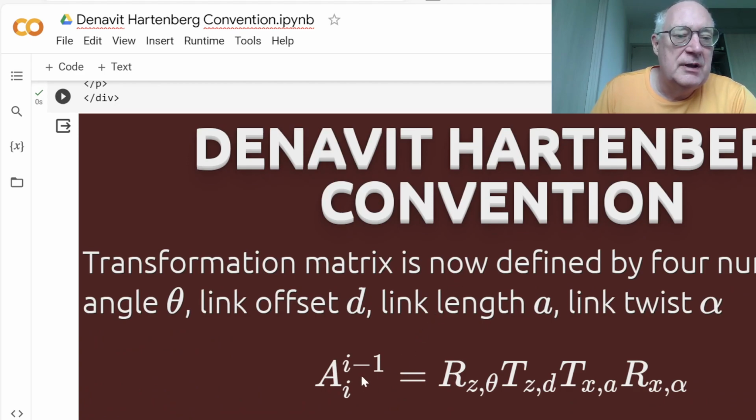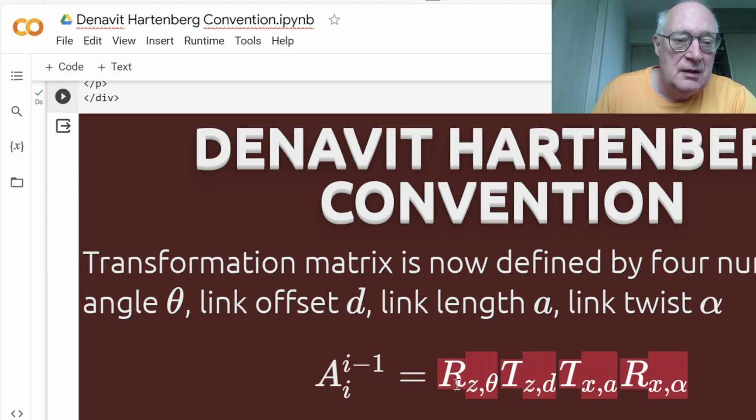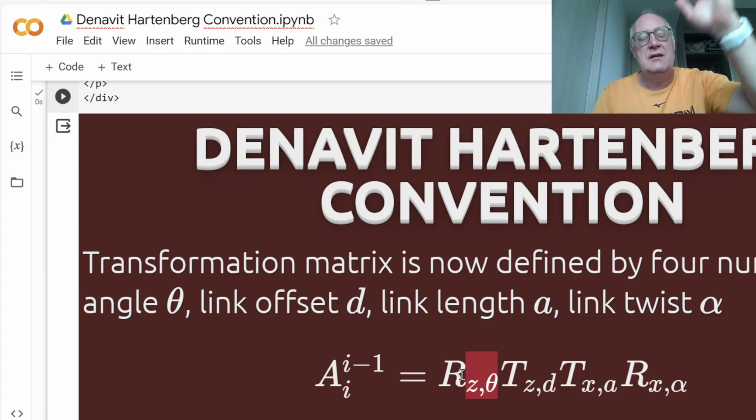So our transformation matrix from i-1 to i is now defined completely by these four numbers, which we get by rotating around z by some angle theta. If we're dealing with a revolute joint, then this would be the actuation, right? Here's where we rotate the links.